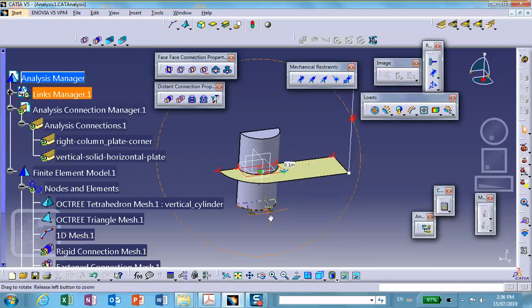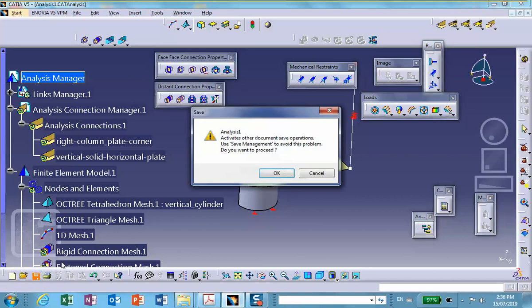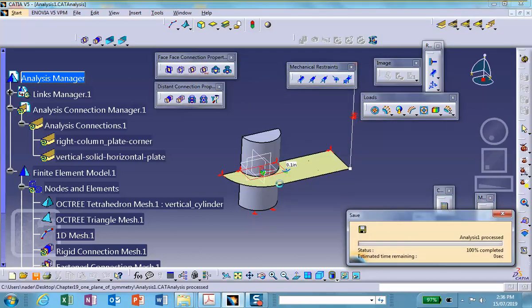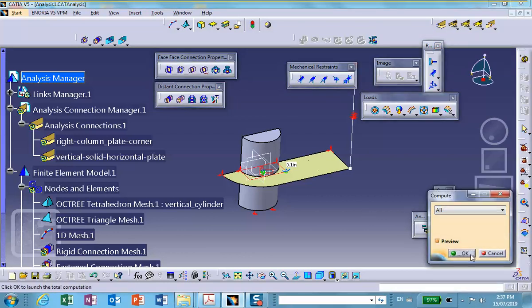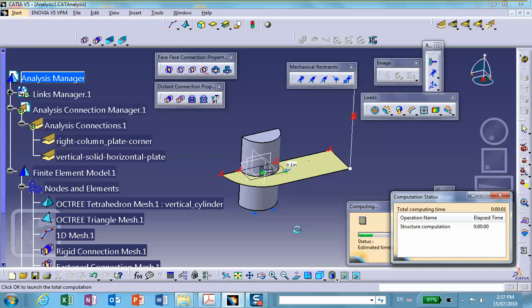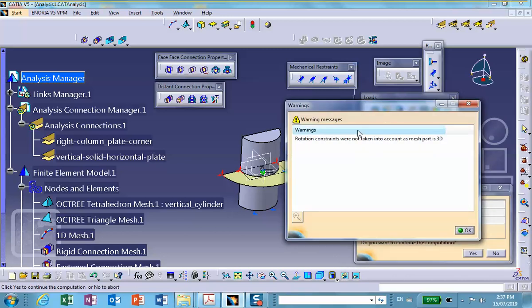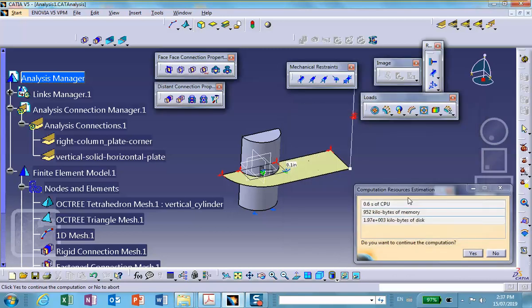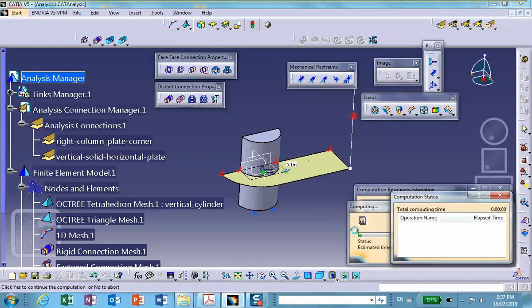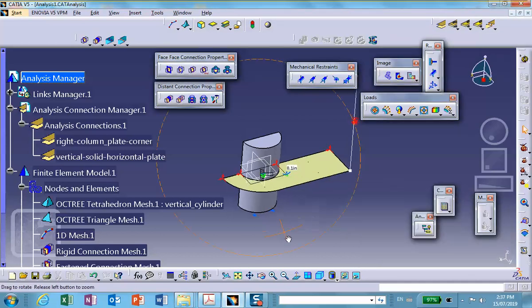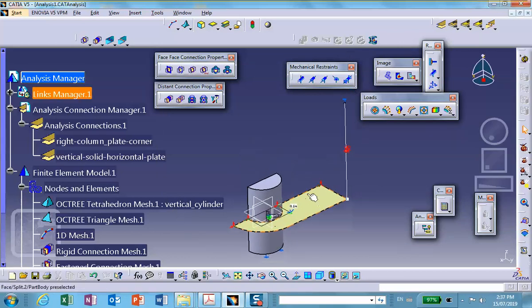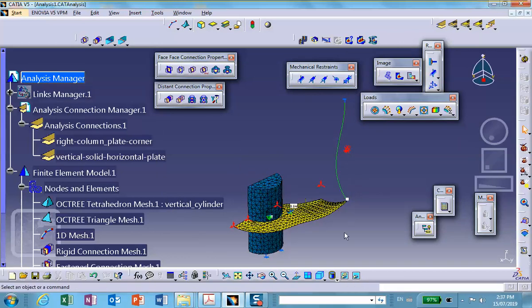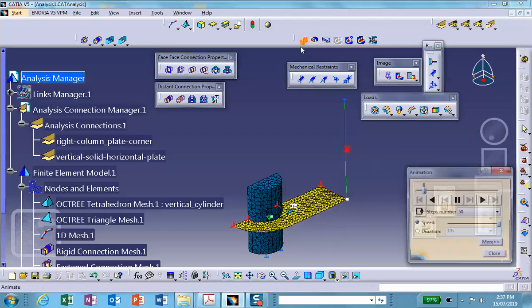All right, so let's run. Well, first of all, save everything, and then we're going to run it. Where's the run? Right there. Hopefully we didn't forget anything. Don't worry about the warning message. It's saying that solid elements do not have rotational degrees of freedom. Okay, very, very good. So let us now look at the deflection. There we are. And you can animate it. And this is exactly the same pattern that we had before.